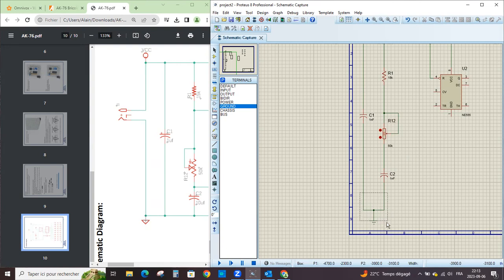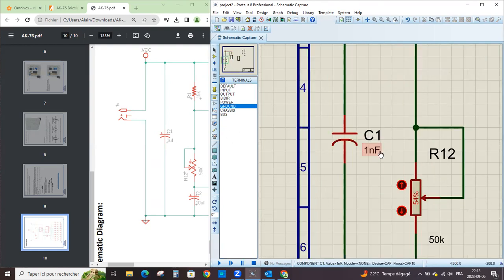A few things. Let's move this resistor. Let's move this ground a little bit. Move it like this, have a little bit more space. I'm getting really close over here, so maybe I'll select the whole thing, move it over. That kind of thing, you look at it at the end. C1 is a 1 microfarad and not a nanofarad like it is here.